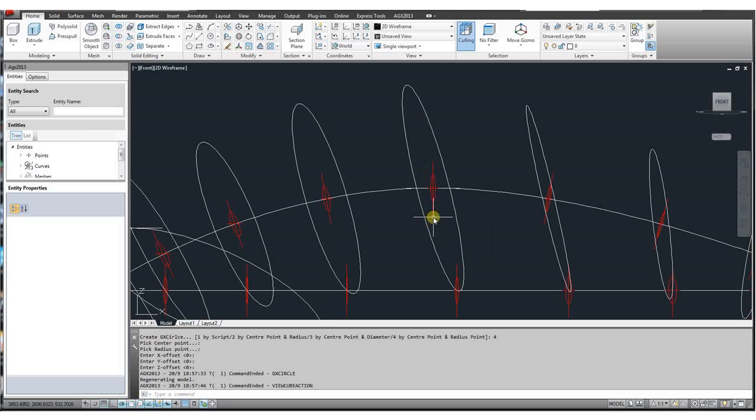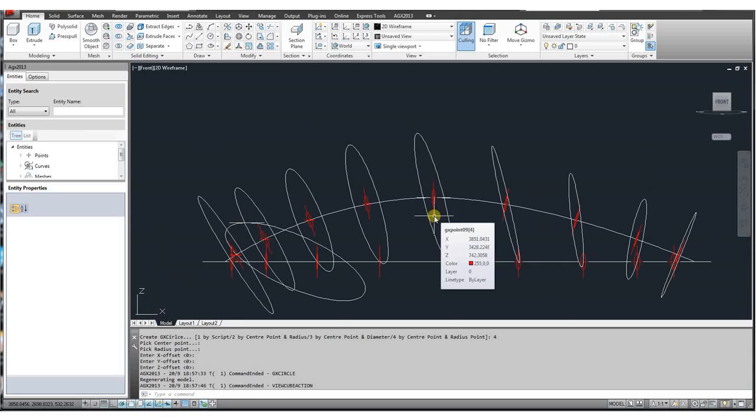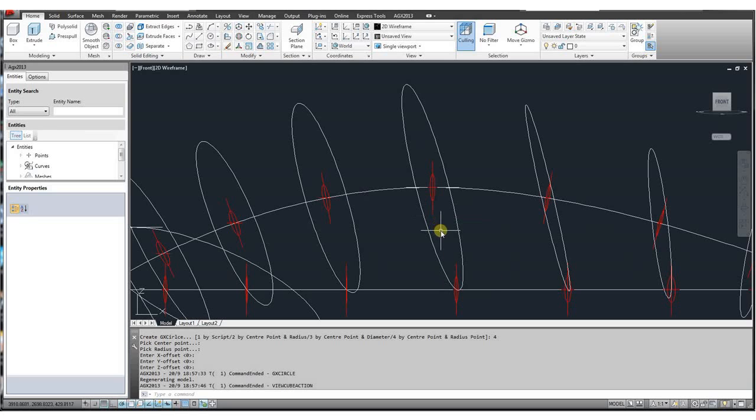That's because the mechanism used to create the plane on which the circle now resides is different to the way the standard circle is created, because it has to find the most appropriate plane which is controlled by the axis between the center point and the radius point, and then the best way to rotate it along that axis so that it's at least controlled by something else, and that is the cross product of the normal of this point.